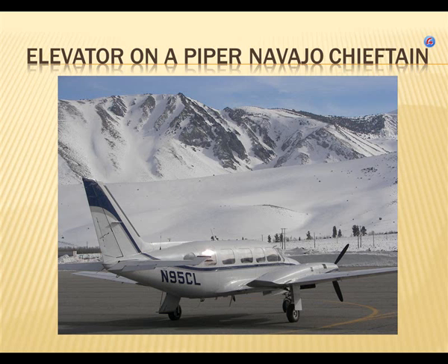So I don't have to use my hands on the control wheel. I don't have to push and pull on the control wheel in order to set the pitch. If I want to fly at 90, I hold the wheel at 90 and then I trim off the pressure, and all of a sudden the pressure goes away, the airplane stays at 90. So coupling this device along with this elevator means that you can set and leave alone the airspeed in nearly every aircraft.